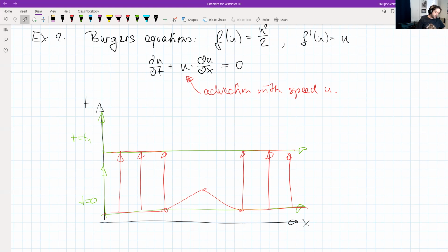And the Burgers equation is that example, and it was exactly designed to be a test problem for Navier-Stokes. It may not have all the properties. For instance, there's no pressure, and in the way that I wrote it here, there's no viscosity. But at least the nonlinearity of the Burgers equation looks very much the same as the one for the Navier-Stokes equations in just 1D. So that's why we typically use it as such.